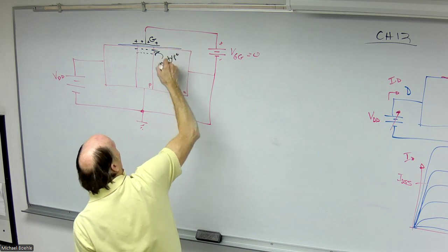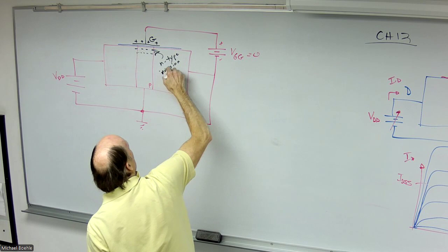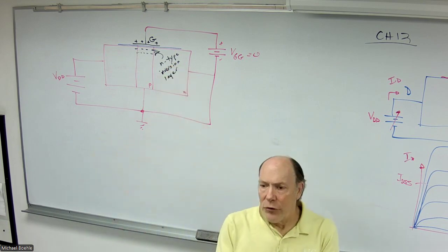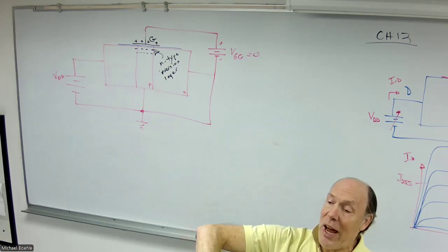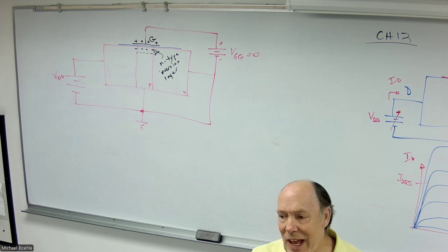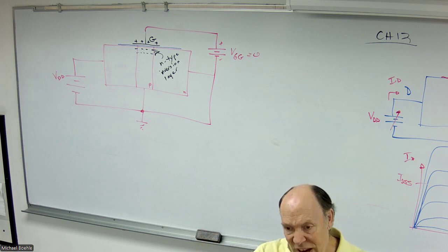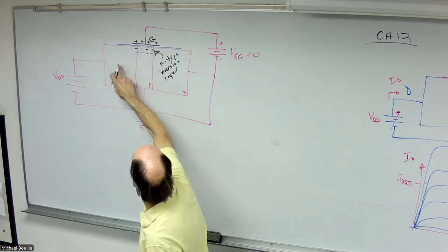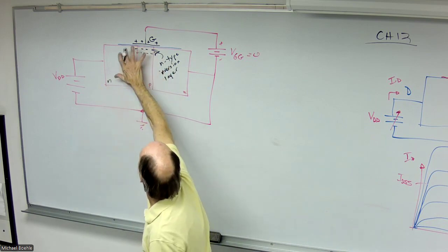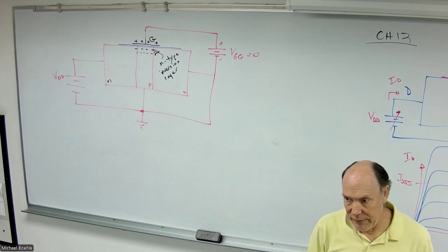Remember, N-type means what? If I say something is an N-type, that means that it has free electrons as its main carrier. So once the voltage on the gate is positive enough, and I pull in enough electrons on the other side of the capacitance, then the holes are filled in. I have enough of the excess electrons to create effectively an N-type material. And now I have N connected to N, and I have current. Make sense to everyone?